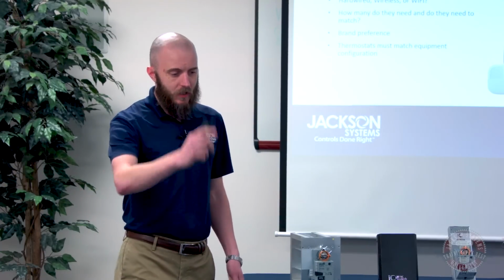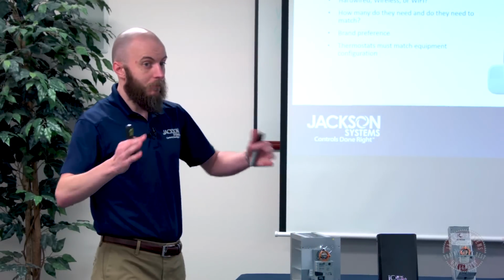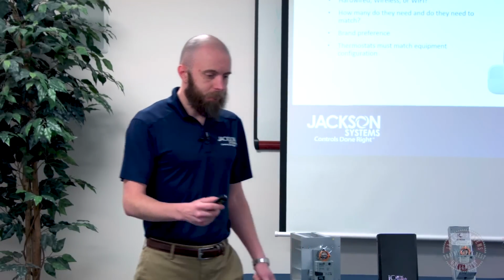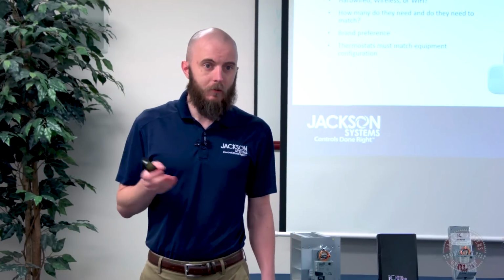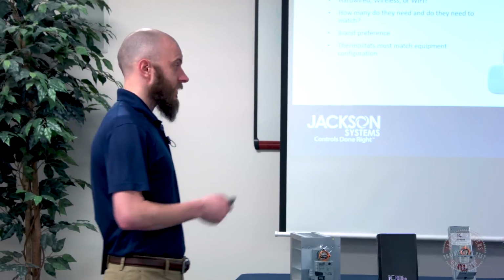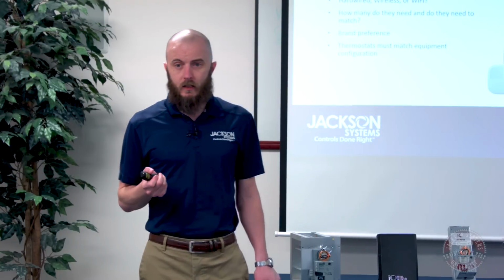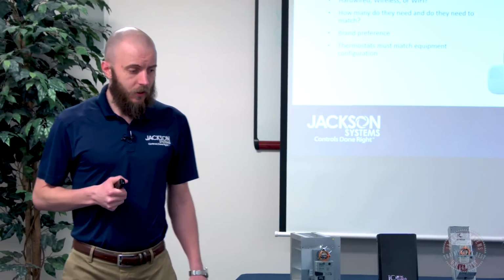So thermostats. We had a question earlier about some thermostats. Most zone panels are going to be able to handle most thermostats. There are a few incompatibilities out there, but they're relatively few and far between. There's all kinds of options. Obviously, a lot of the focus and a lot of the excitement these days is around the Wi-Fi thermostats and your smart thermostats. For the most part, these are going to work just fine on most of your zone panels.